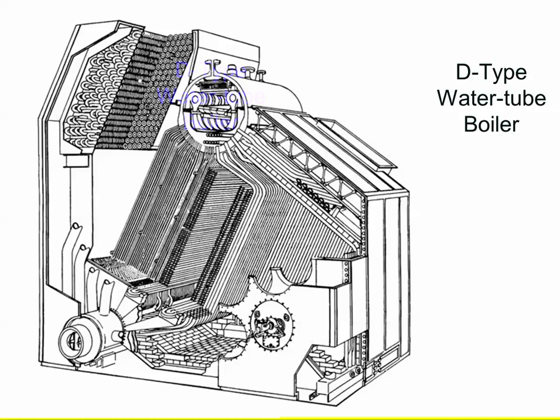They always have to have strictly either air on startup, or more typically when you're running, steam inside them, and you have a gas-to-gas transfer, not liquid to gas like we do in the generating tubes. That means these superheater tubes are very, very subject to overheating and failure if you do not have a competent boiler operator. It is a high concern in a motor ship.